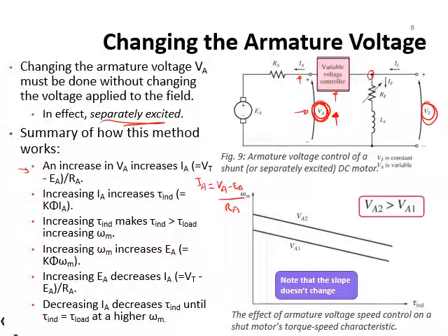Okay. So this voltage on the right hand side of the resistor minus the voltage on the left hand side of the resistor, over RA. So the voltage difference across RA divided by the value of RA, that will give you the armature current IA. Okay. So the slide is not exactly right, it's supposed to be VA here.